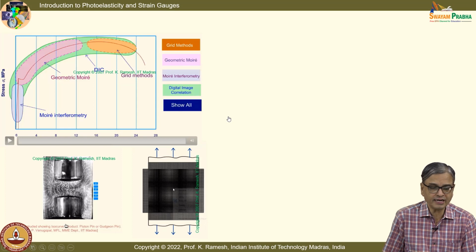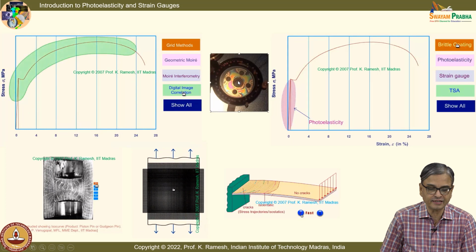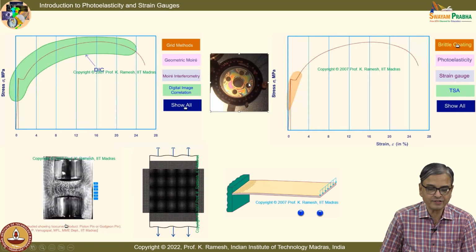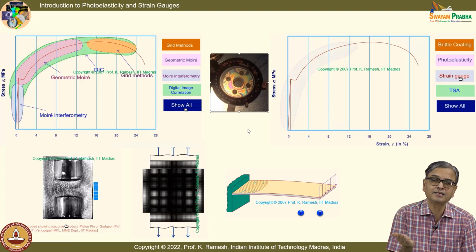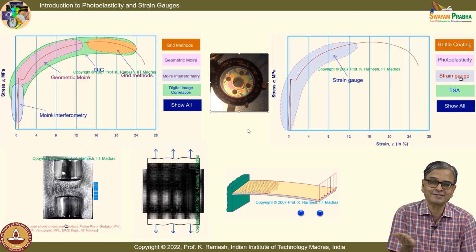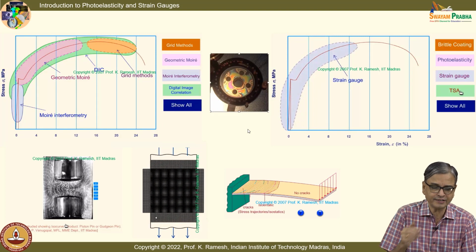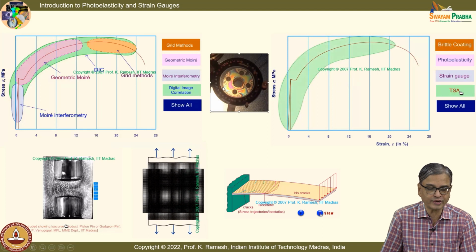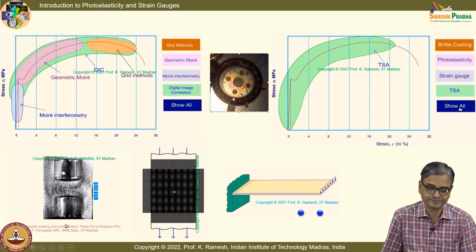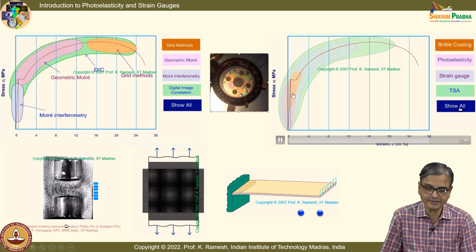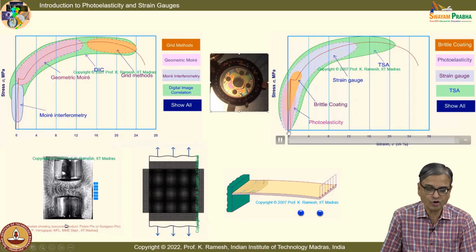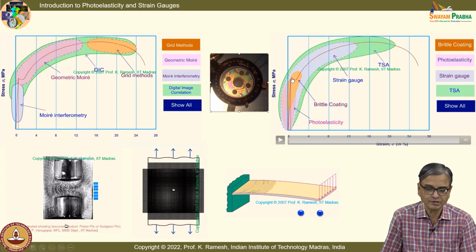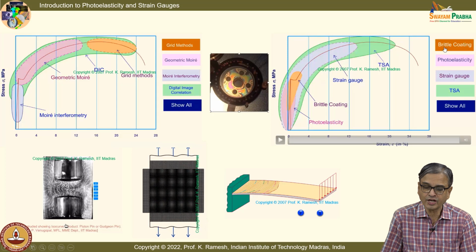And we have also looked at photoelastic coatings, and in the reflection scenario, you have the coating bonded onto a specimen. So, the strain from the prototype or the specimen is transferred to the birefringent coating. So, it is strain induced and you get beautiful fringe patterns. So, you have photoelasticity which is in this range, complete elastic range from almost close to 0 strain to till yielding. Then you have brittle coating.